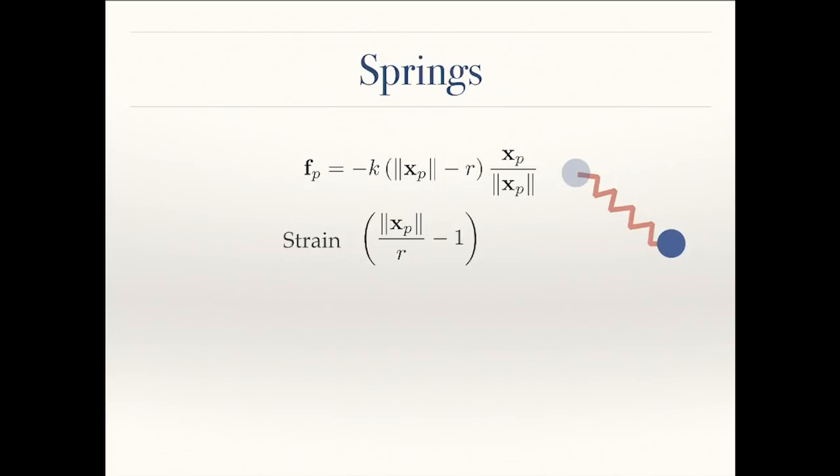So if you have some simulation mesh and you have some k associated with it, and then you refine that simulation mesh, if you're using a strain metric, then you don't have to change your material properties. They are independent of the resolution of the mesh. If you look at when we had the rest length actually showing up in our formula, that puts some meters in there. And that means that our k then depends on meters, and it makes things more complicated. Okay, so we substitute in this strain metric,